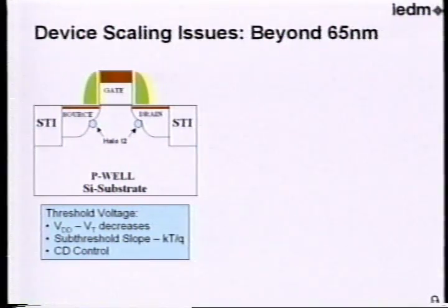We still have the junction isolation that we've had in the past. You have the gate dielectric here. We've been using halo type implants to suppress short channel effects and so forth. So the standard transistor is this kind of device, and it's being used everywhere.